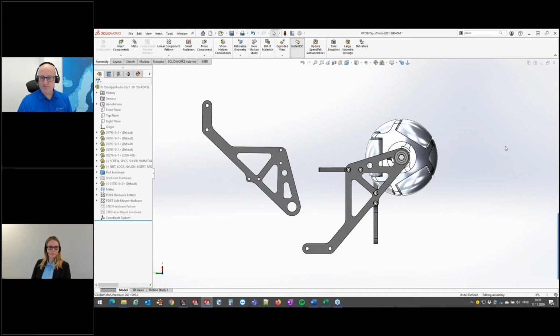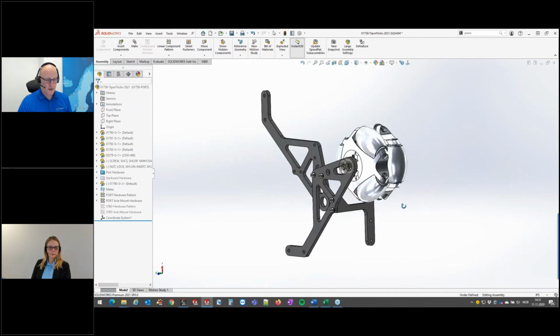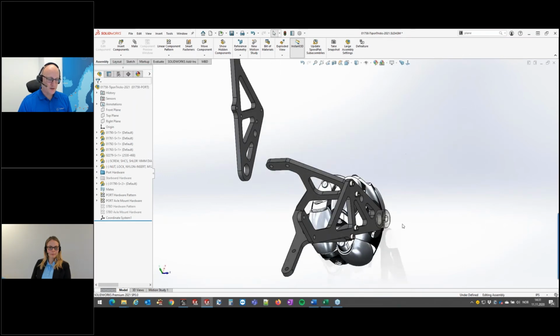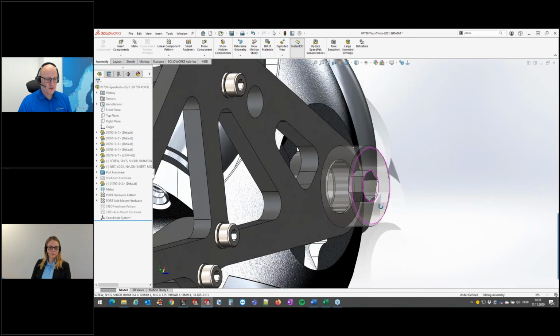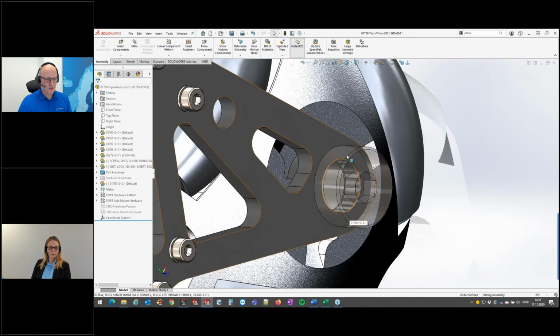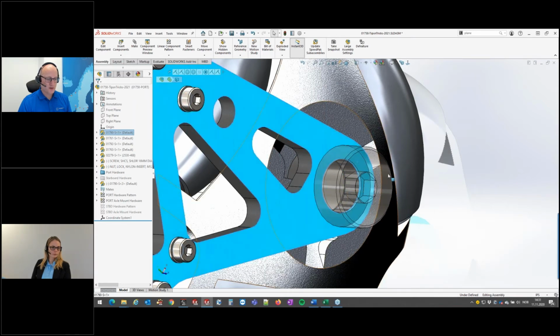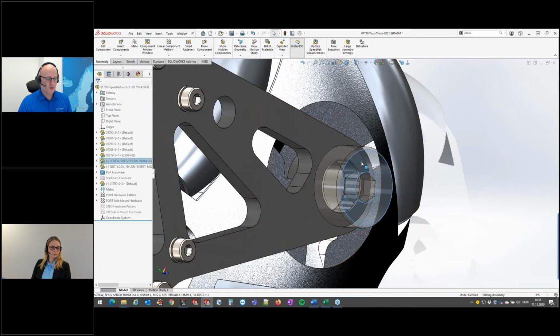All right. The last thing we are going to look at is this transparent bolt here. If I click this transparent bolt, SOLIDWORKS will insist on selecting whatever is behind this transparent component. This is how SOLIDWORKS works by default. What you can do is to press the Shift button and then click the bolt, and then you can select the transparent graphics. Okay, so Shift Select makes you select transparent graphics. All right, I think that's it for tips and tricks so far.